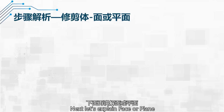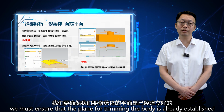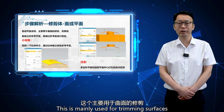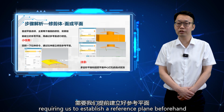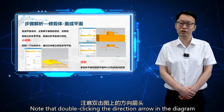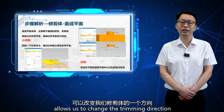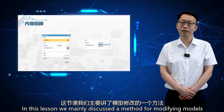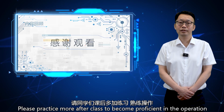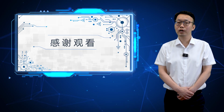Next, let's explain Face or Plane. When the tool is set to Face or Plane, we must ensure that the plane for trimming the body is already established. This is mainly used for trimming with surfaces, requiring us to establish a reference plane beforehand and trim using the reference surface. Note that double-clicking the direction arrow in the diagram allows us to change the trimming direction. In this lesson, we mainly discuss a method for modifying models, specifically the use of the trim body command. Please practice more after class to become proficient in the operation. See you in the next lesson.